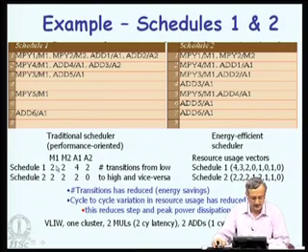So, 2 transitions for M1, similarly 2 transitions for M2, M2 is used here and then it sleeps. A1 actually has 4 transitions. A1 was asleep to begin with, now it has woken up, then it is used in cycle 2, then cycle 3, then cycle 4, and in 5 and 6 it is idle, so it goes back to sleep mode, then again wakes up for cycle 7 and then goes to sleep again. So, there are 4 transitions as far as adder 1 is concerned and 2 for adder 2, adder 2 is used only in cycle 2.